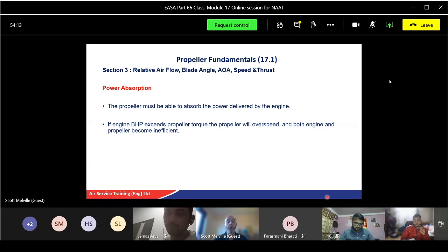You might only end up with 100 horsepower, and that's your brake horsepower. It is your indicated horsepower, what in theory should be that engine power, minus everything that's attached to it. For your car, you'd have gearboxes, your rear wheel drive, front wheel drive, whatever it is, the power at the wheel. In our case, it's the power at the propeller. Okay, so brake horsepower is the indicated horsepower minus the parts you've taken off.